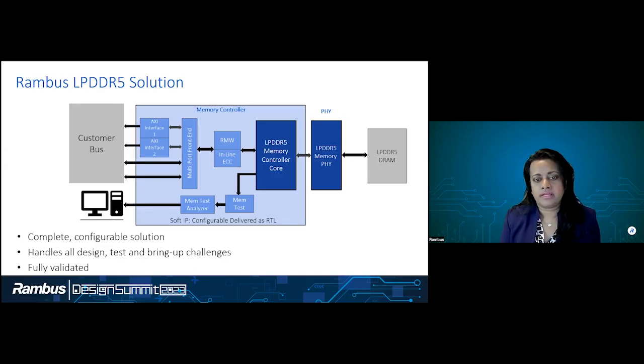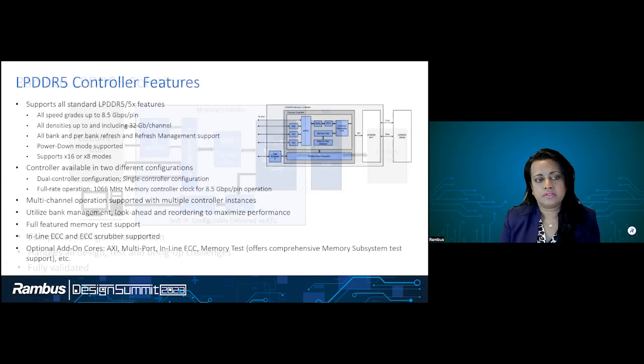And when we provide this solution configured for your needs, we will also provide it with a complete reference design, as you see with the light blue box. This is provided as soft IP deliverables. Now, the interface between the memory controller and the memory PHY is based on the DFI 5.0 standard. So with that, let us dive next into the LPDDR5 controller features itself.